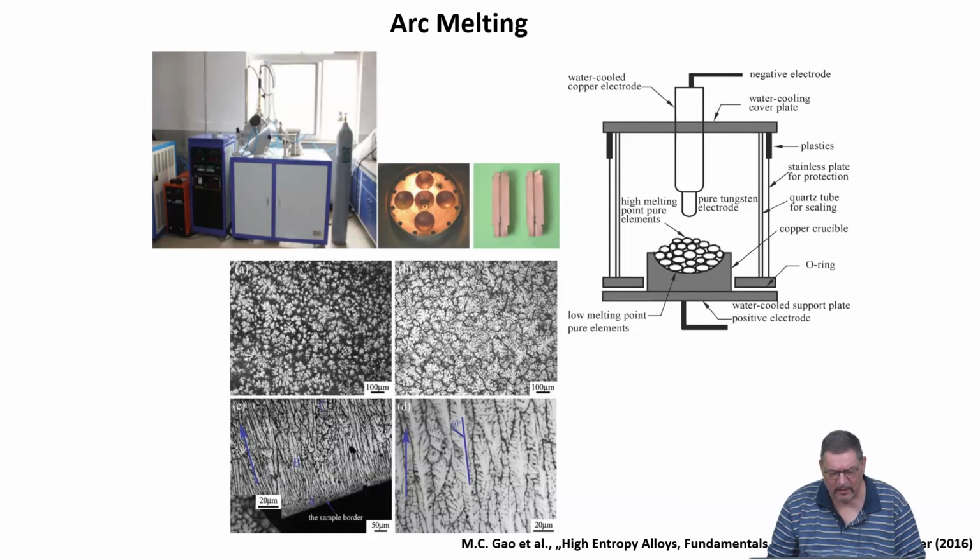Also, as indicated here, you get very complex microstructures because you have a rapid heat flow to the cold copper hearth, which means you have directional solidification, but not in a uniform direction, basically spreading everywhere. And a very rapid heat extraction favors the formation of a supercooled liquid. When you have solidification in a supercooled liquid, you know that the solid-liquid interface can become unstable, which means dendrites can form. Then you get a highly directional and fractal crystal phase forming that often doesn't have good properties.